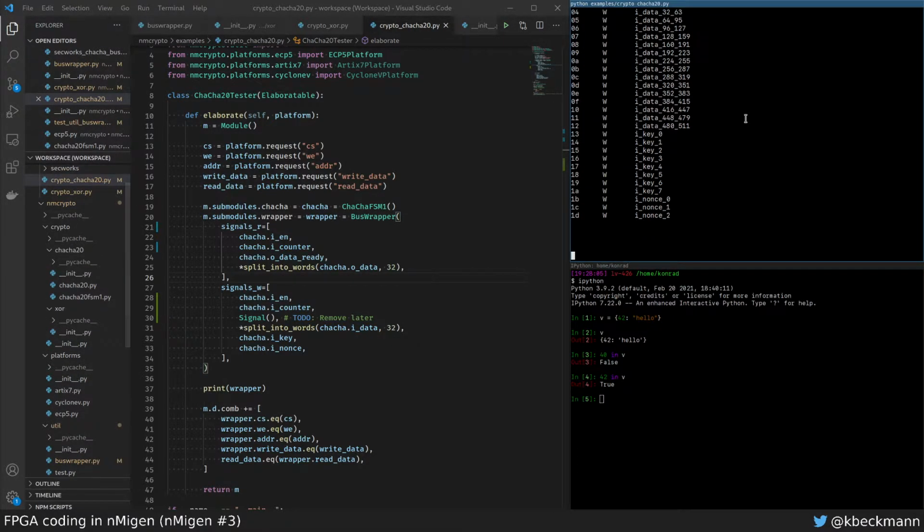Okay, here we go. So for some reason, when you're building with nMigen and yosys and press Ctrl C while yosys is running, it will not kill the process.